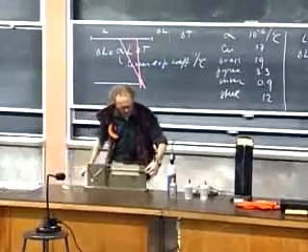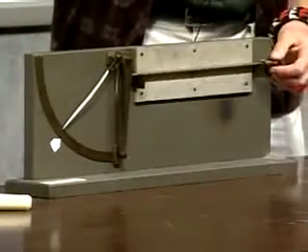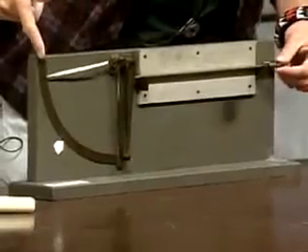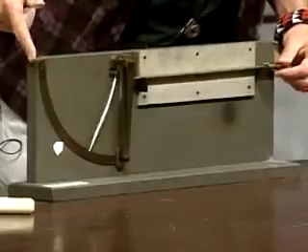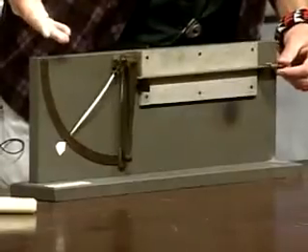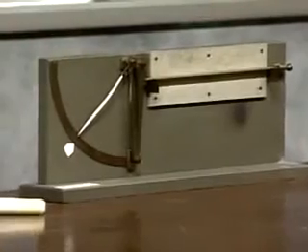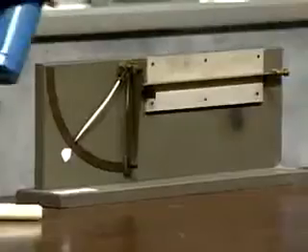I have here a set screw, and I can move the bar in this direction. I'm not making it longer, but I can move it, and you will see what effect it has. If I move the bar one way, it goes up. Move the bar back, it goes down. You can think of this as a thermometer. It will be 70 degrees, as it is now. And if I heat it up, then it will get longer, and you will see this end go up. Let's try that.